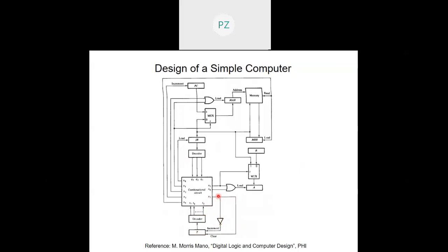And finally, X7. See, X7 clears the counter or resets it to 0. And if X7 is not there, it has to increment. This is active low counting. That is why I'm seeing an inverter here. So whenever anything other than X7 is there, it keeps incrementing, so from T0 there is a transition to T1, then T2, T3, T4, and whenever X7 goes high, regardless of where this timer has reached, it will reset it to 0. So that is why X7 is taken as clear and X7 bar is taken to increment, right?